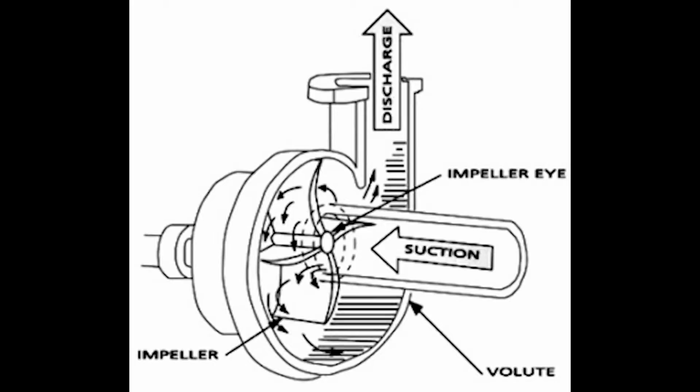Centrifugal pumps use an impeller made up of curved vanes to transfer mechanical energy to pressure and kinetic energy in the liquid. The impeller is immersed in fluid, causing the fluid to rotate with it. Centrifugal force is applied to the water particles, causing them to move radially to the edge of the vanes, where they reach a higher pressure and are channeled out of the discharge nozzle. The pressure in the eye of the pump helps to suck the inlet flow into the system.